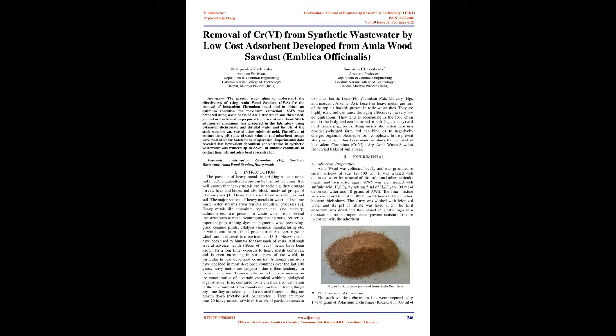The effects of contact time, pH value of stock solution and adsorbent dosage were studied under batch mode of operation. Experimental data revealed that hexavalent chromium concentration in synthetic wastewater was reduced up to 83.2% at suitable conditions of contact time, pH, and adsorbent concentration. Keywords: adsorption, chromium 6, synthetic wastewater, Amla Wood Sawdust.